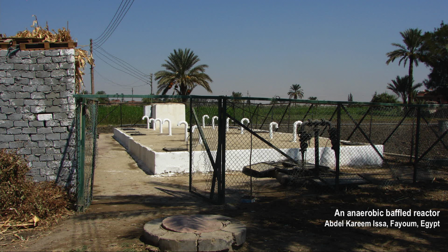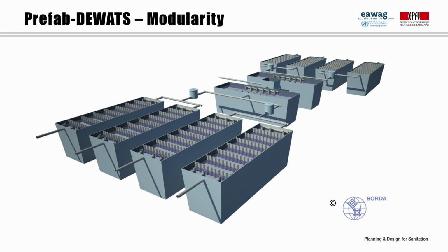However, if the ABR looks simple, one should not forget that, as all the treatment systems presented here, it relies on biological processes. It is like a living organism. The startup period is crucial to reach an optimal performance and requires expert follow-up, at least for the first 6 months. The ABR is particularly appropriate for small-scale, or sometimes called decentralized, wastewater treatment plants.